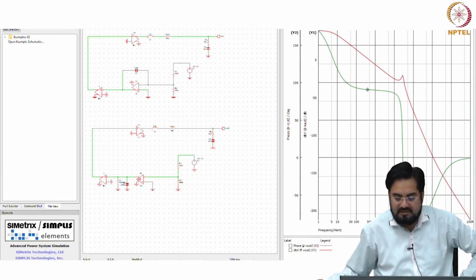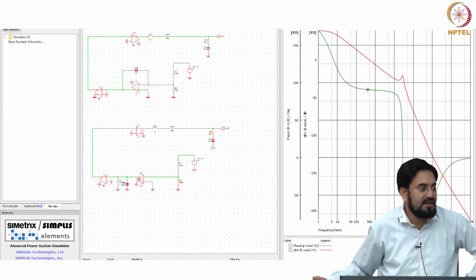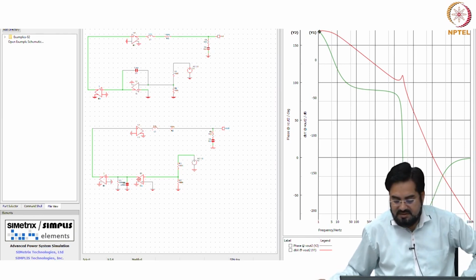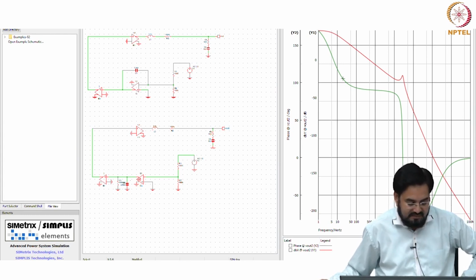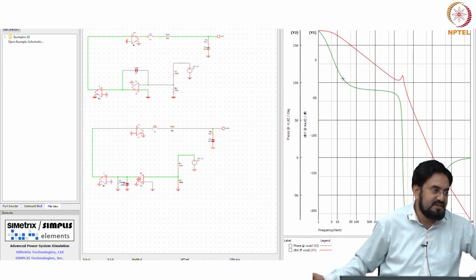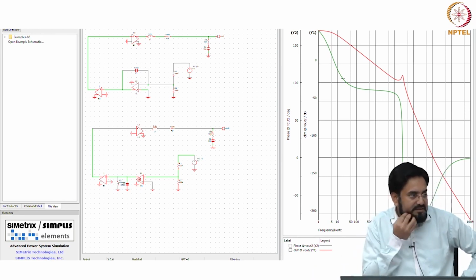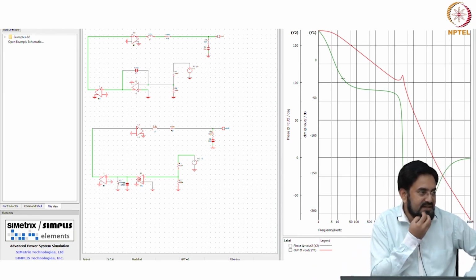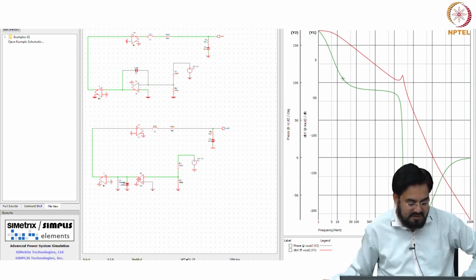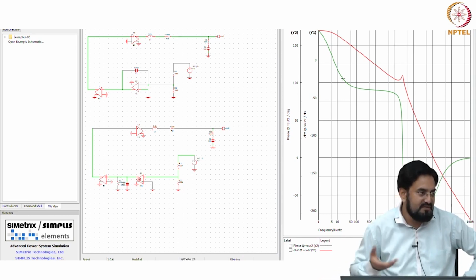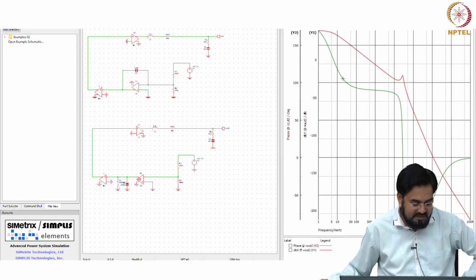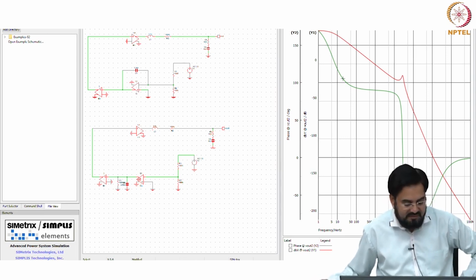This integrator will cause 90 degree, okay. The reason you are seeing it starting 180 is because I have a resistor here. So, your DC phase shift will not be minus 90, which is for the integrator. The reason I have put it is because it is a floating node, so the simulator will not converge. So, you have to put a high value resistor here. It is a 10 mega. If I increase this to giga ohm, maybe this curve will shift here.